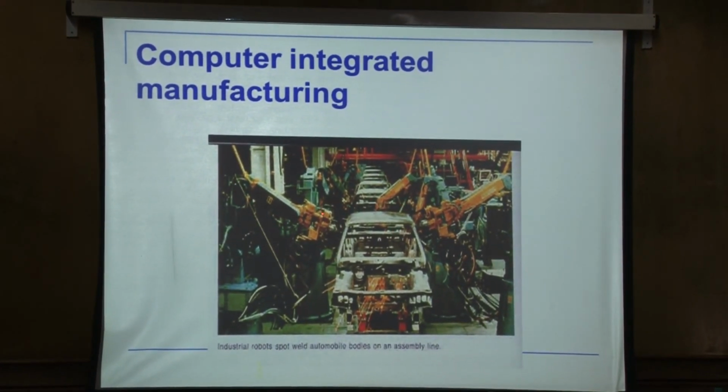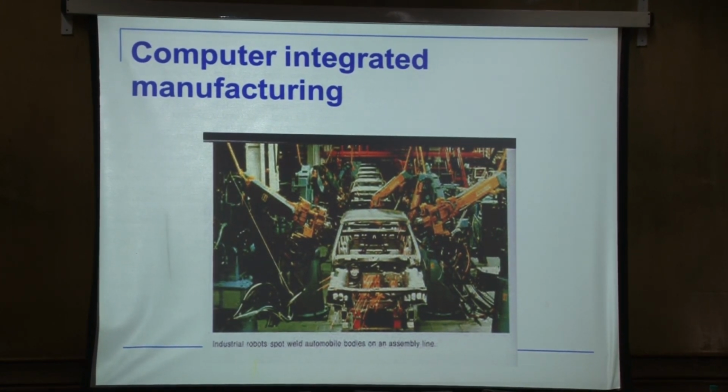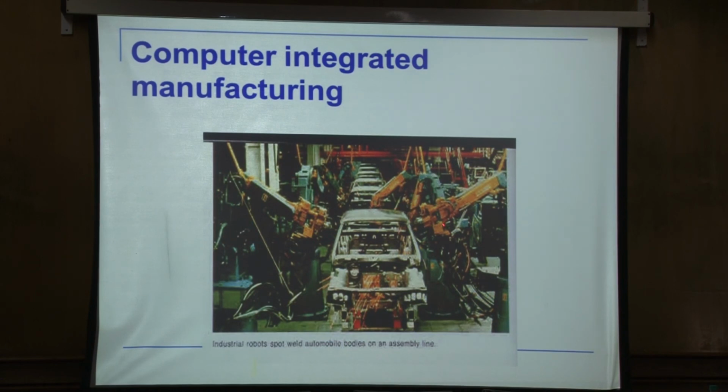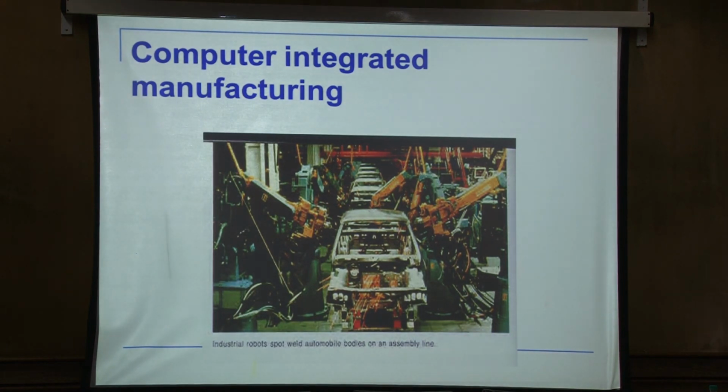Now, if you're trying to program this kind of a robot, although it appears that programming is very easy, actually it's not, because if you try and program for this, not only must it get inside very complicated spaces, but it should also avoid hitting the object, and not interfere with the other robots which are operating. And on top of that, your cycle time should be optimal. Because a little bit of delay also causes problems. It causes a lot of change over a large number of cycles. So this is the reason why robot programming is very, very specialized.